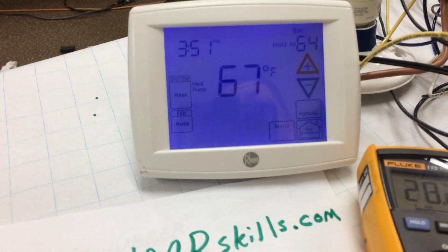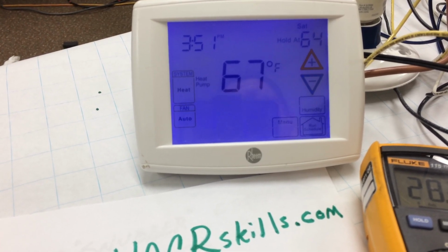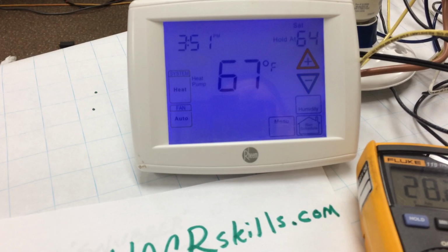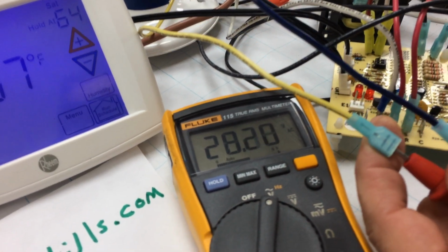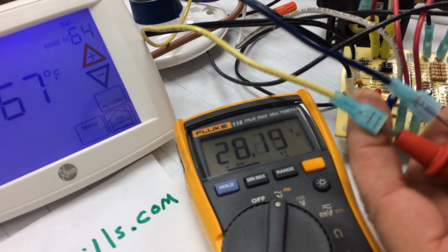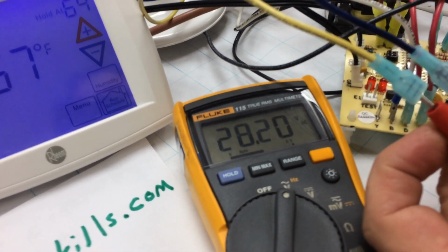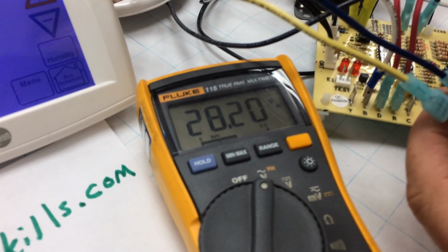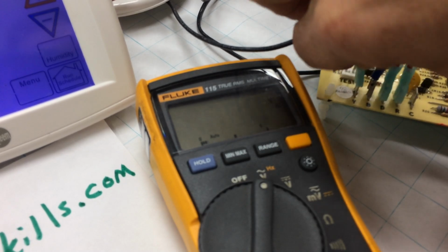This thermostat is not calling for operation. We've got 67 degree room temperature, a 64 degree set point. We are not calling for any heating operation. But once again, on common and Y, the wires themselves, I am reading a 28 volt signal here. These very same wires, when I plug back onto the control,